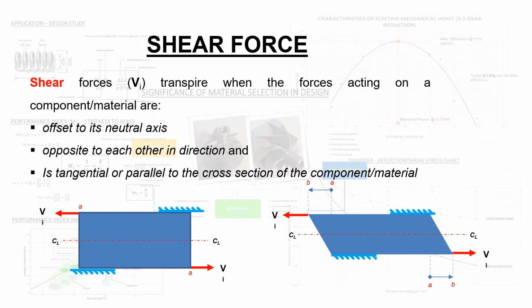Before we look at shear stresses in a bit more detail, we need to think about what shear forces constitute. Over the past couple of chapters, we've looked at situations where the applied force is coaxial to the center line or the axis of a given component. So what if we have a situation whereby the applied load is offset? It is collinear in terms of the plane of deformation. However, the force is at an offset to the central axis as shown in the diagram.